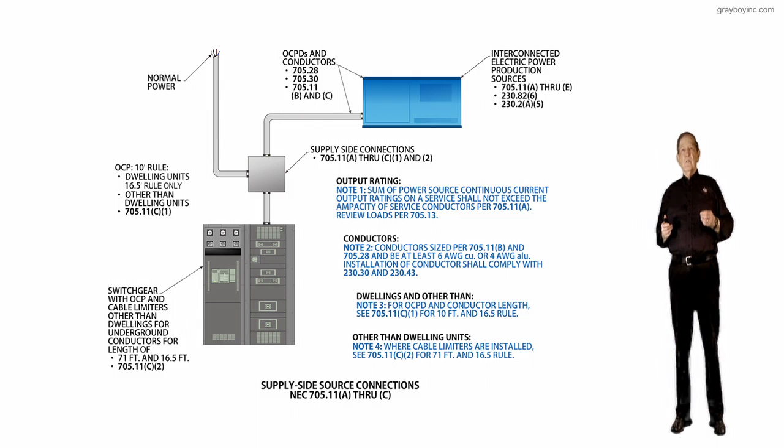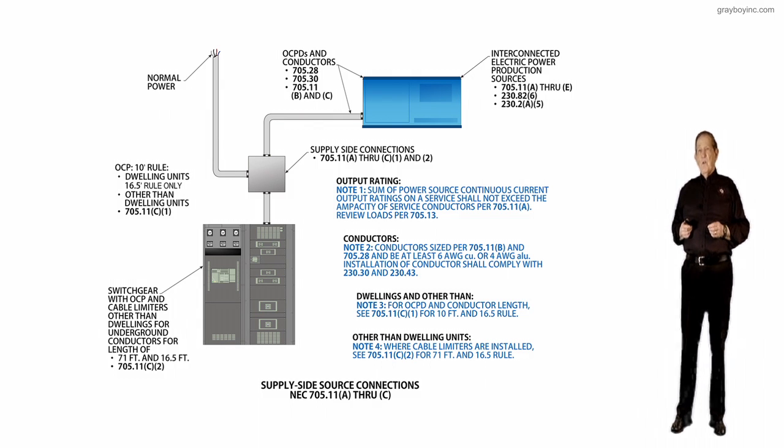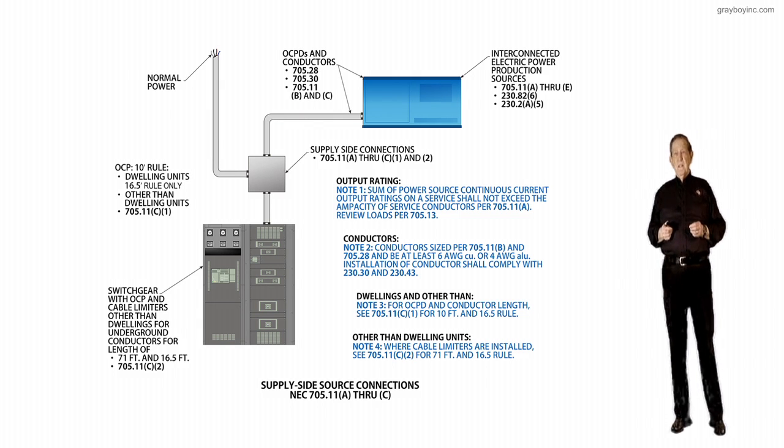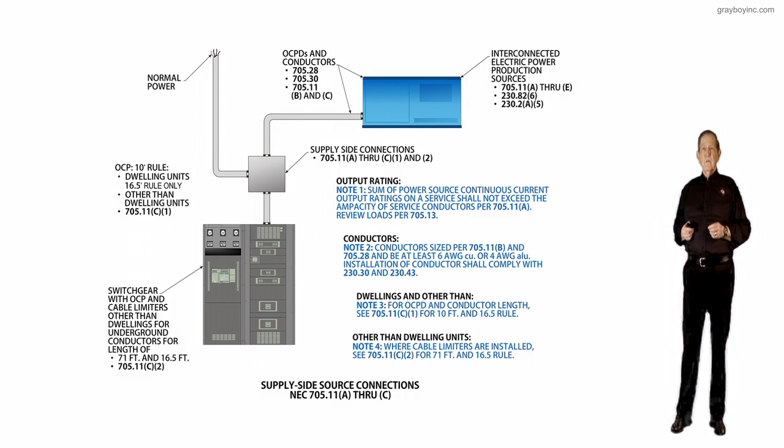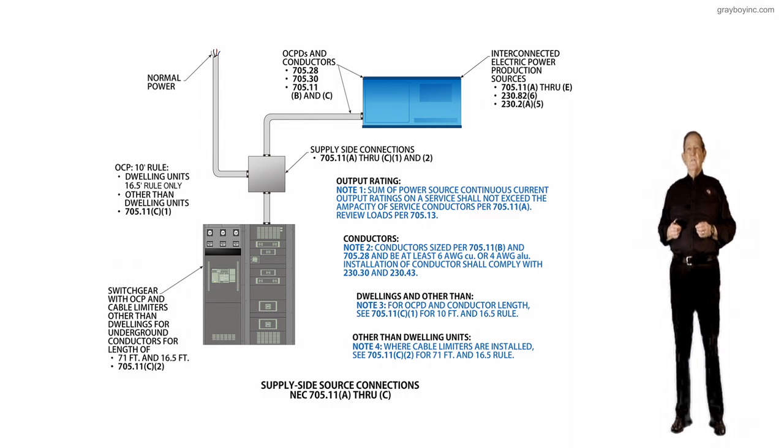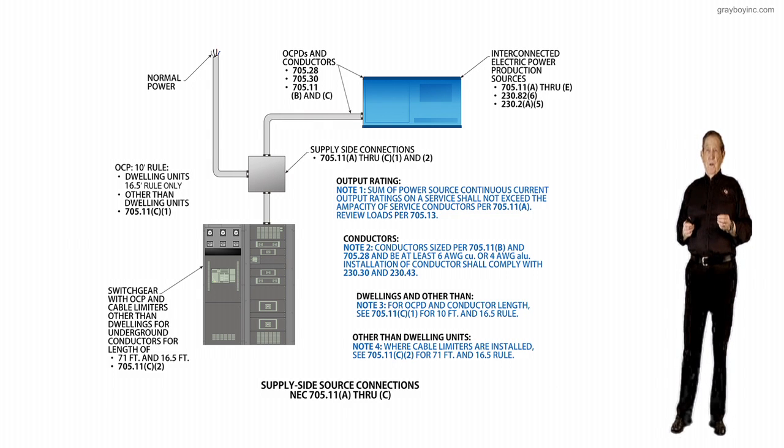In some cases, for some loads, you may apply a demand factor. Demand factors are less than 1. Where the authority having jurisdiction will permit it, some engineers on some high voltage feeders may apply a diversity factor, which is more than 1.